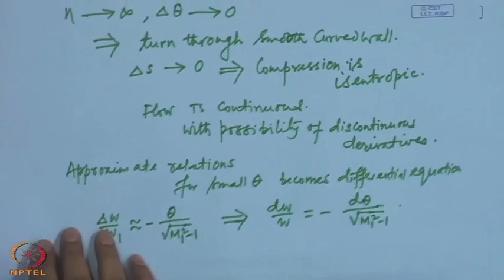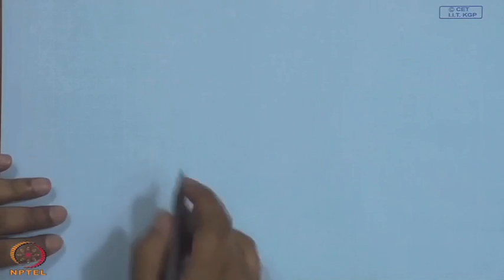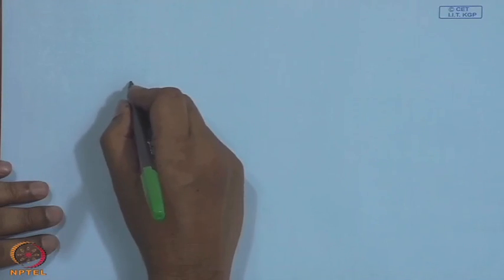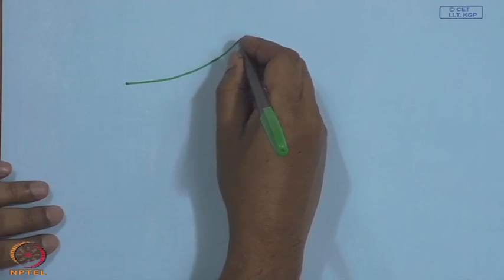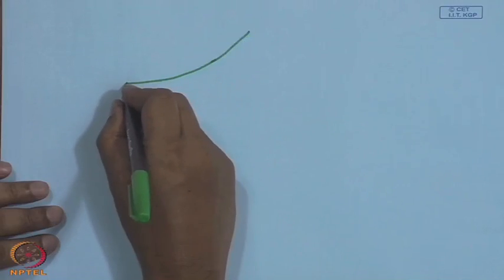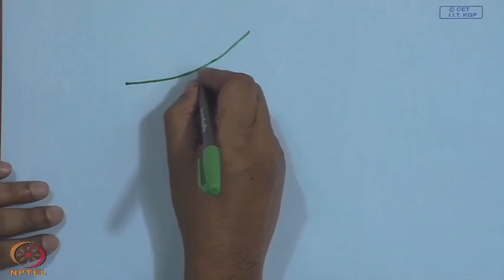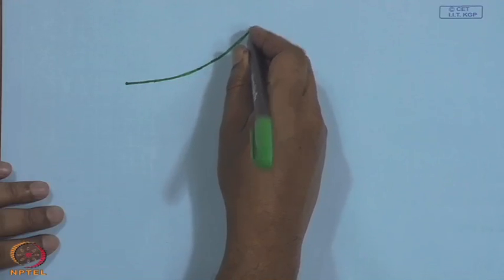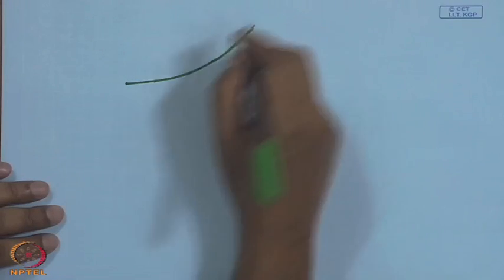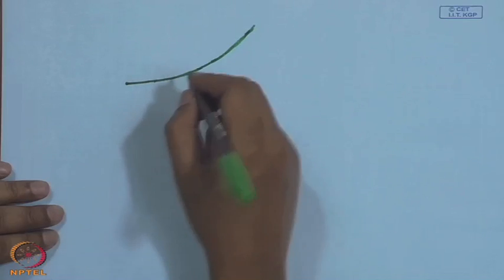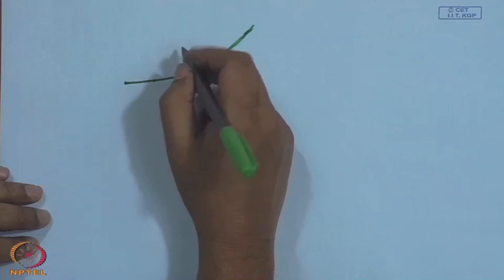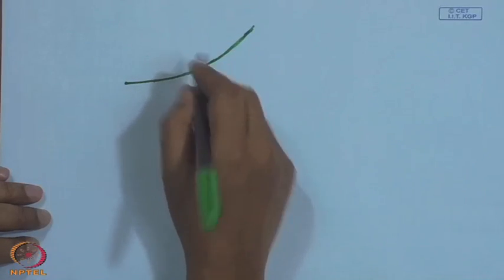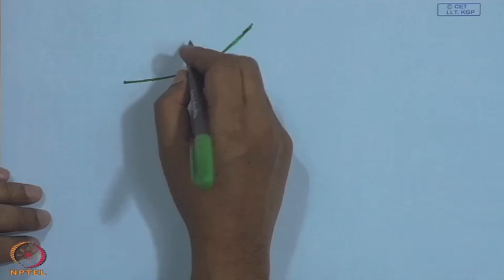Now, let us see this configuration close to the wall, where there is no sharp corner, but the wall is turning smoothly, and similarly there will be a very weak shock from each point, and those shocks are almost the Mach lines.